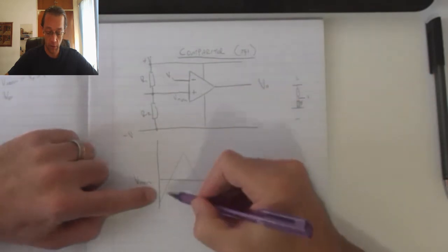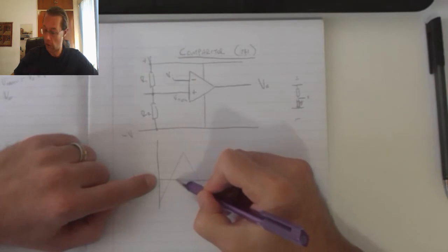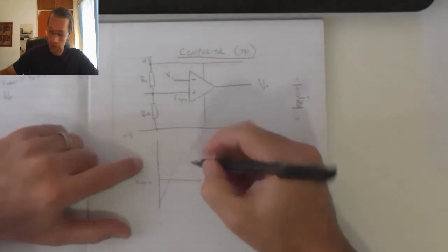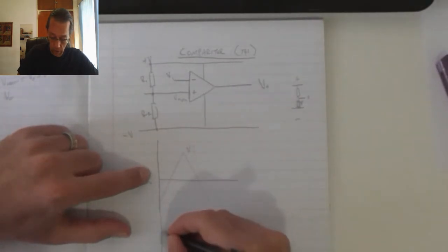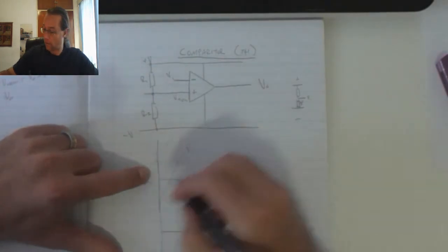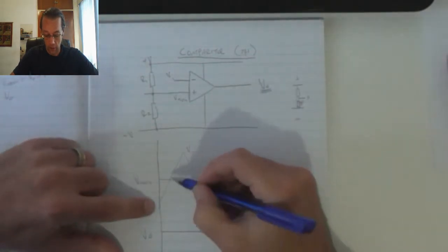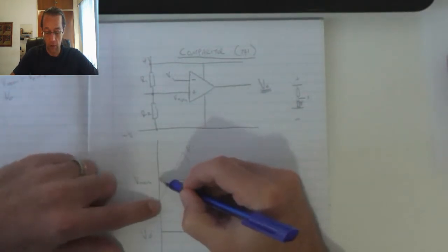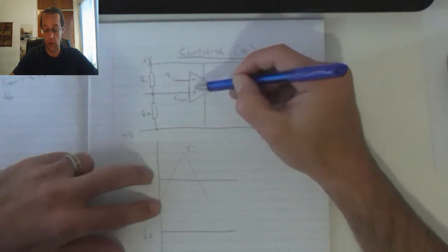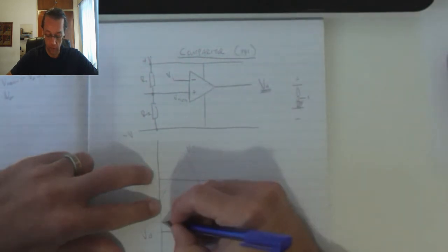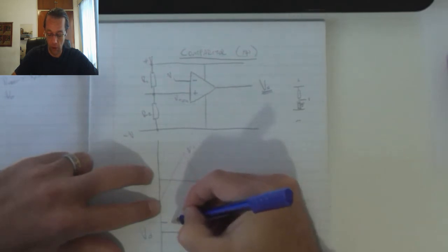we can see at this point we've got a voltage less than my non-inverting input. This is V in. As a result, what's going to happen on the output, V out is blue. So at this stage, my non-inverting input voltage is larger than my inverting input. As a result, my output will switch to the positive saturation, and it will remain there up to that point over there.